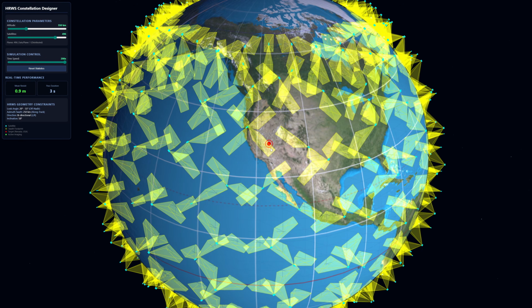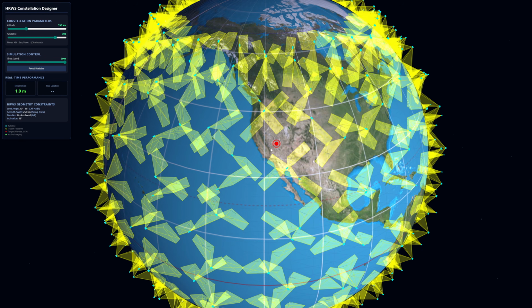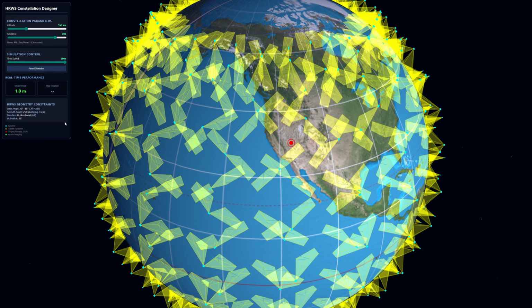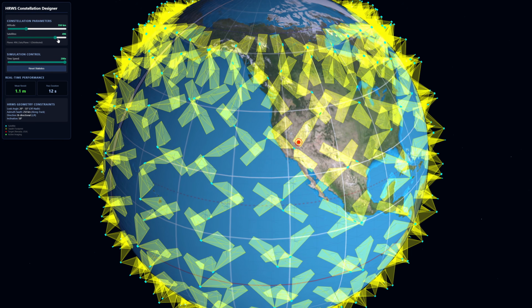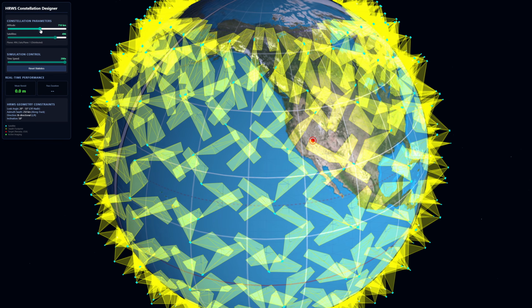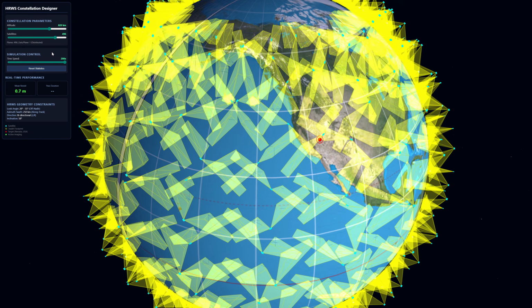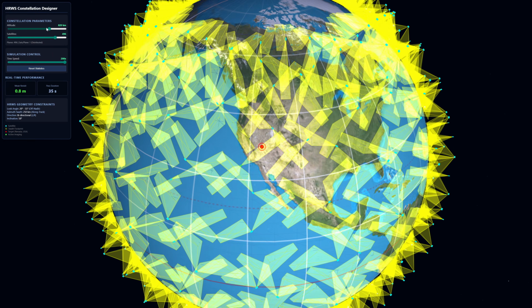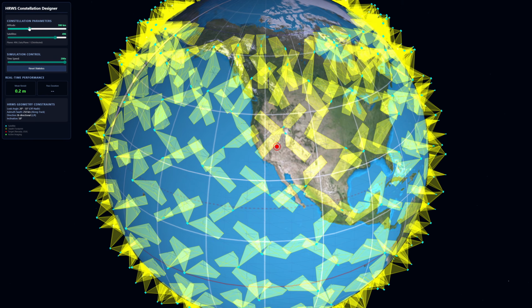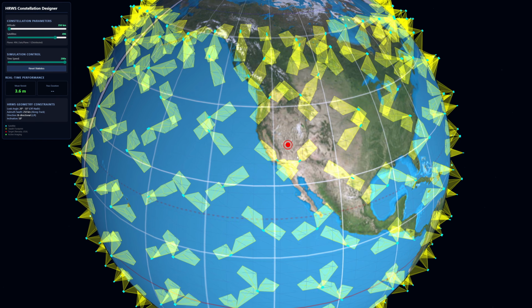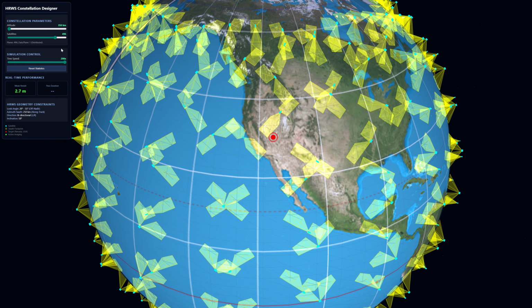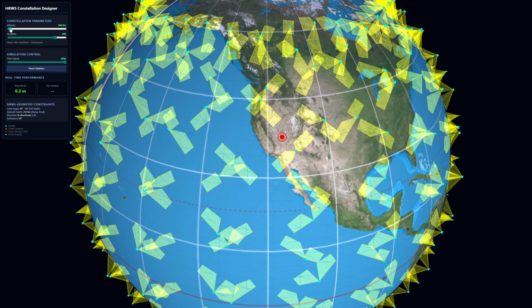The range swath would only fill part of the yellow region I animate, and this would be adjustable, and of course this would just be on one side of the satellite at any given time. So the revisit time for the entire Earth would be much longer than for a given high priority target area. The size of the swath would also become smaller in the range dimension for a high PRF air moving target indicator mode. A ground moving target indicator mode could have a much wider range swath, and the azimuth swath could also be reduced to create redundancy for space-time adaptive processing. I should also mention that these could be very flexible satellites that could switch between a combination of many different modes, including the VideoSAR spotlight mode I showed earlier.